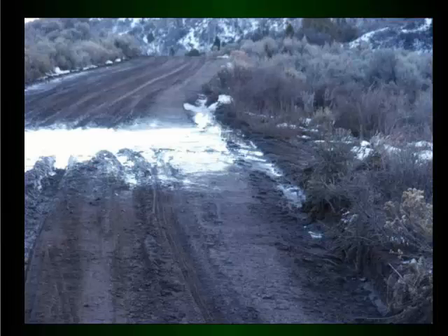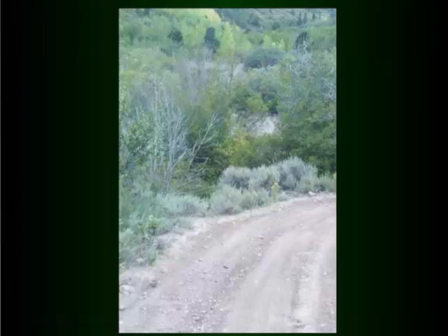Another mud hole, just basically a situation where the water needs to be taken from one side of the road to the other with a pipe, and probably the road needs to be built up just a little bit here so that it's not a depression. And once again, put a little bit of crown on the road. It's a situation where you got a little bit of a berm on the outside, and you can see a pretty good rut coming down this road here.